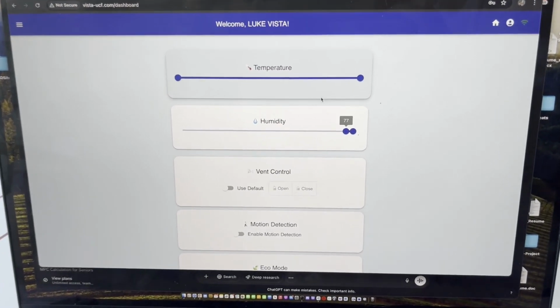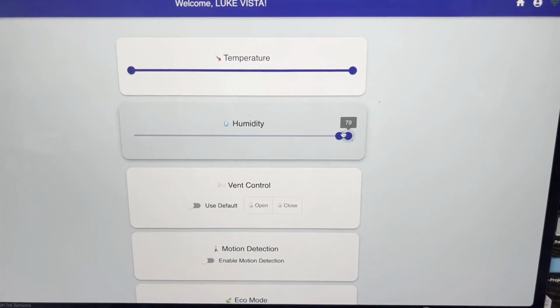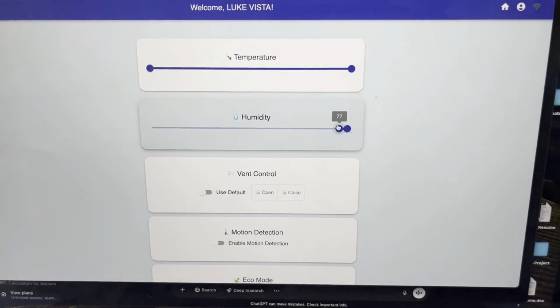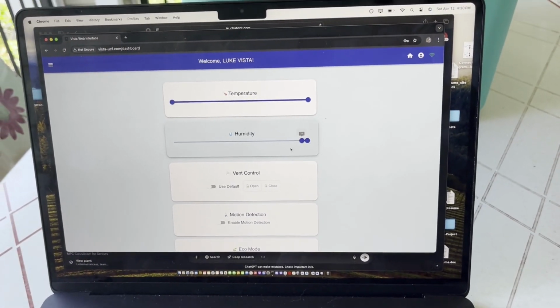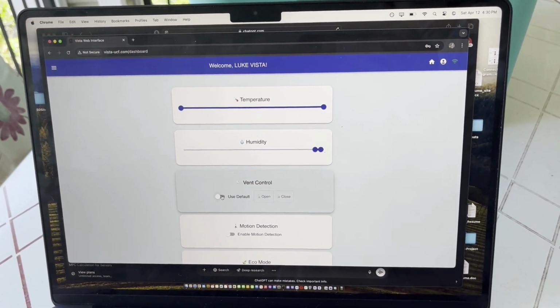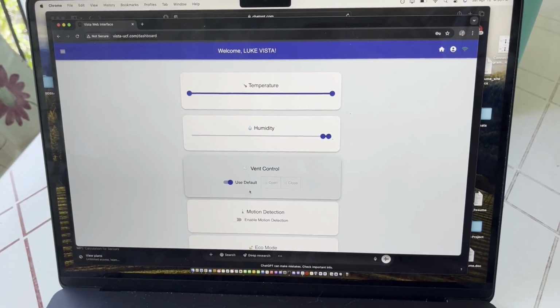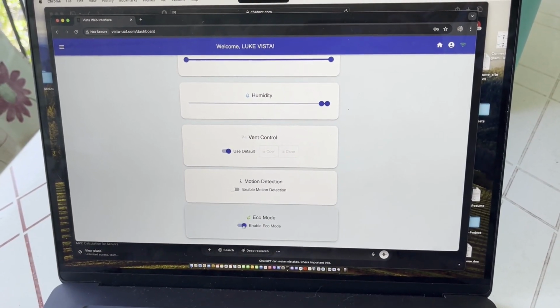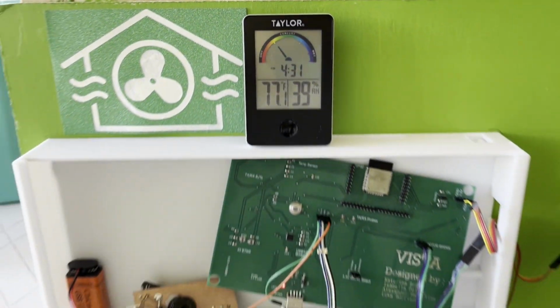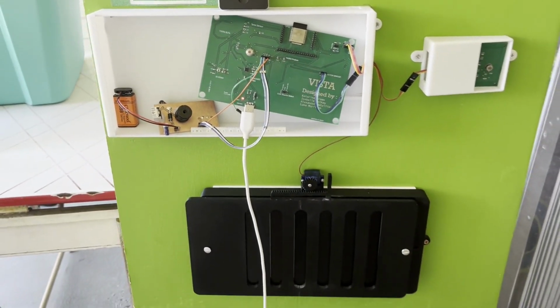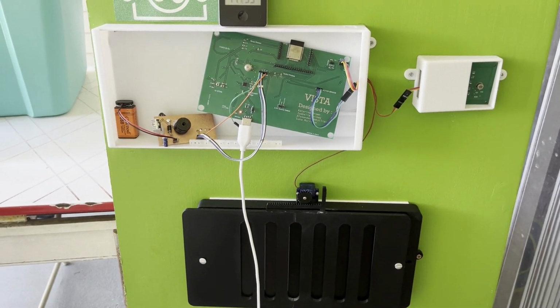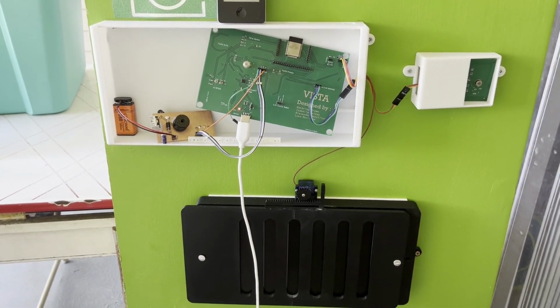The second scenario is based on the occupancy and humidity sensors. This mode is called vacancy mode. The idea behind this mode is for when users are out of town and care less about the temperature settings within the home. The user can configure the temperature and humidity specifications for vacancy mode to ensure minimal energy usage is used. The vacancy mode ensures that the temperature and humidity within the home stay within a certain range as the user specifies.